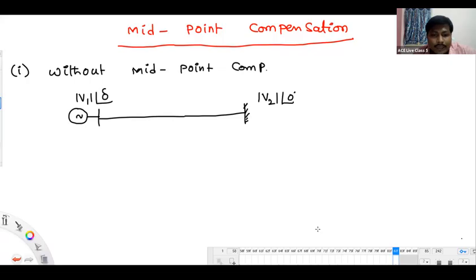Improving steady state stability means, one thing, you should get the difference between steady state stability limit and steady state stability. Steady state stability limit is P maximum. Improving steady state stability means increasing the value of dP by d delta. In that, P max increment is one of the options. Cos delta naught increment is also another option, right?